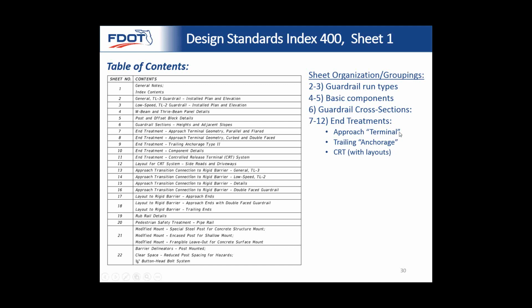If you look at the APL and you're looking for end anchorage assemblies, it'll still say end anchorage assembly, and then in parentheses it says approach terminal. After about a year or so, we'll drop the end anchorage assembly. It'll just say approach terminal, and that will be the official new term. And essentially, we're following AASHTO. AASHTO defines end treatments as the blanket. So if you're ever confused about, well, what do I call that thing that goes on the end of Guardrail? I'm not really sure. If you say end treatment, that pretty much covers them all.